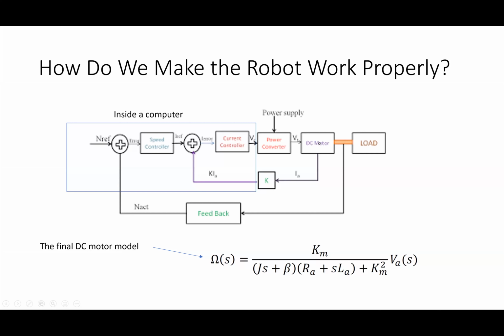And what I do is I measure maybe the position or the speed, and I feed that back, and I then have a control system that determines exactly what voltage I should apply to this motor to get it to do what I want it to do. All right. To do that, I need a mathematical model.